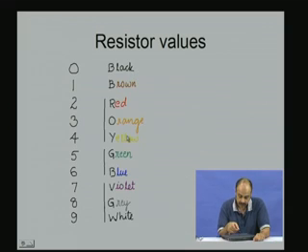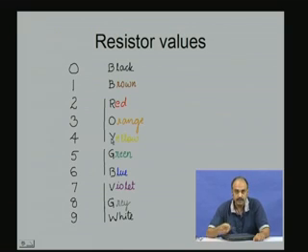Now, it is pretty difficult to remember the order in which the colors are written. Therefore, we normally have a key. You look at the first letters: B, B, R, O, Y, G, B, V, G, W. These two are phrases, G, B and V, G, W, which you can remember as phrases. G, B is the short form for Great Britain, V, G, W is the short form for very good wine. So, you can remember the whole color code as B, B, Roy, Great Britain, very good wine, which will give you the sequence in which you can remember the color codes which represent the numeric values.